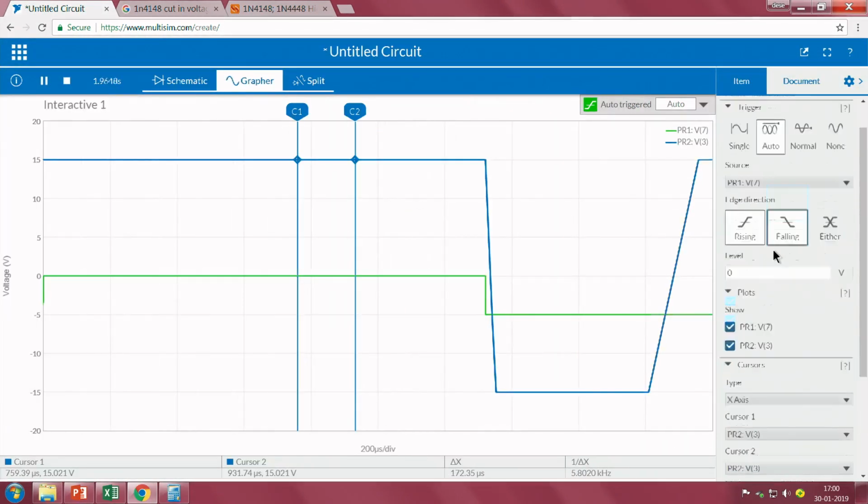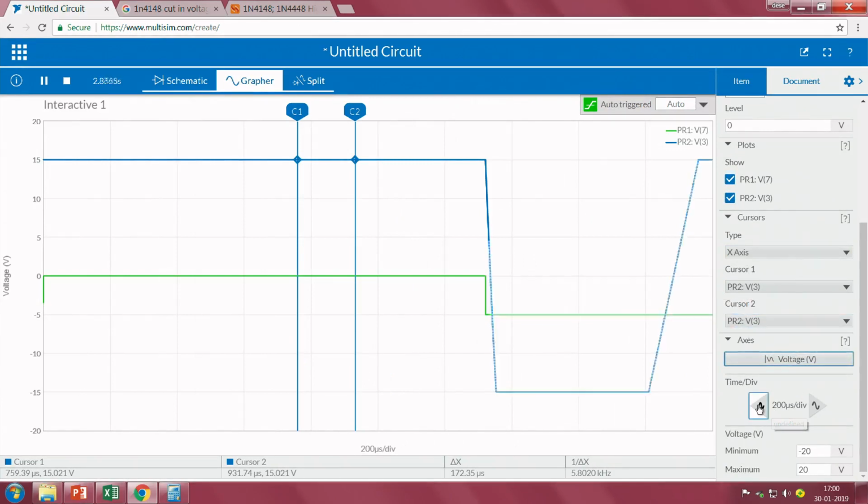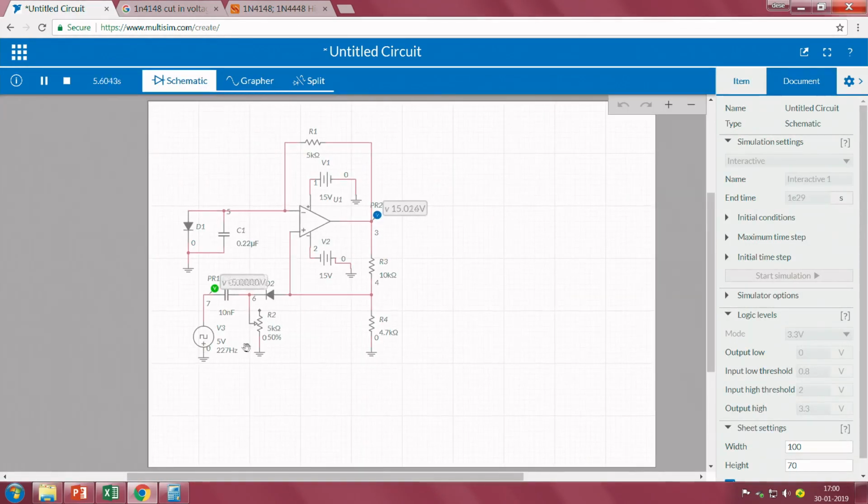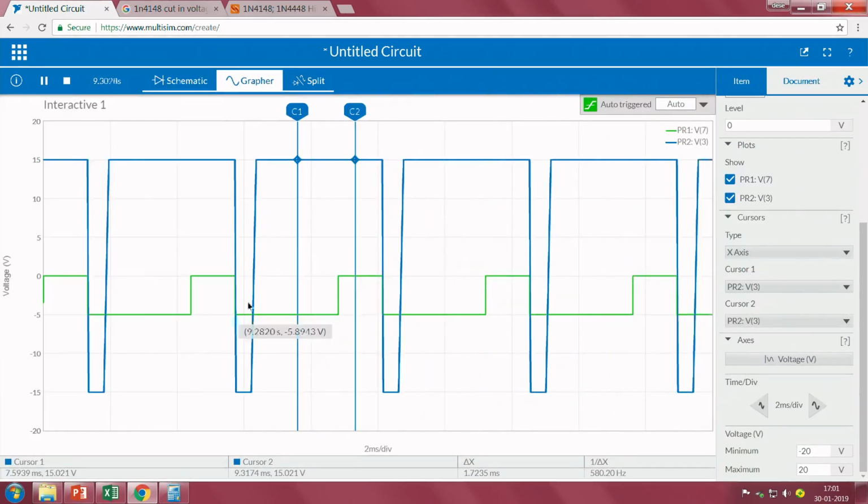Right now, since our time duration is smaller, in this case there won't be any problem, because we are operating at a very low frequency. When you invert it to get the time, we have enough room for the capacitor charging and discharging. Even in this case, whenever I have a negative trigger, I have a pulse till I get to the next negative trigger. The positive trigger will not be considered, and only during the negative trigger am I getting a fixed duration on time, then off time. So there is no missing of signals.